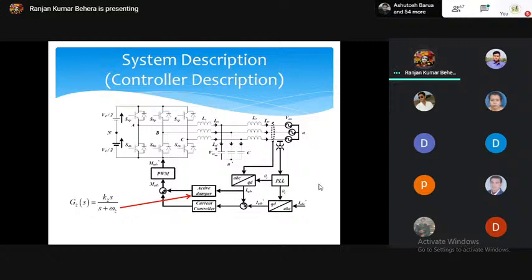low resistive path. Okay. So when you have an LCL filter and you want to filter out at resonance, you need to choose proper frequencies, because the resonance depends on the plant parameters, for example L and C. And the switching frequency depends on your power converter. If it is 20 kilohertz, for example an IGBT, it can switch up to 20 kilohertz. So according to that, you have to choose your switching frequency.